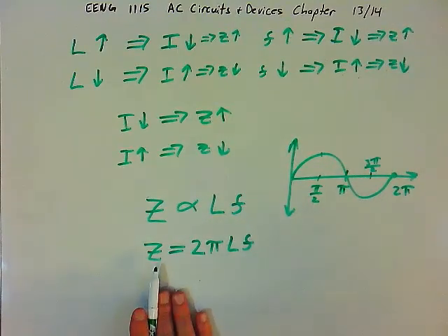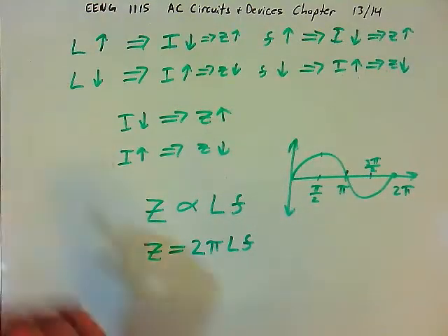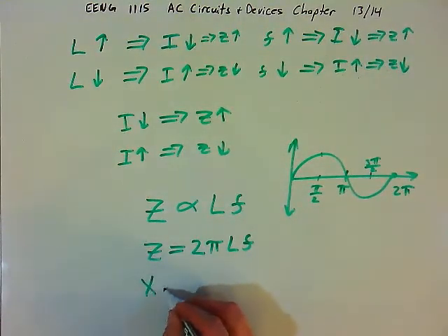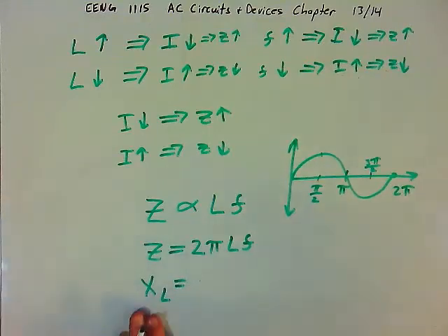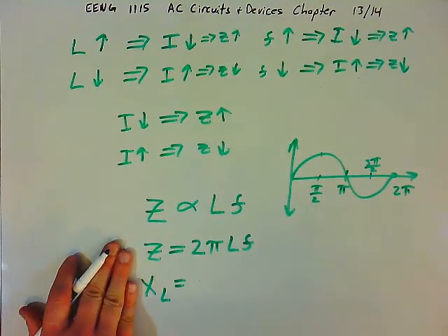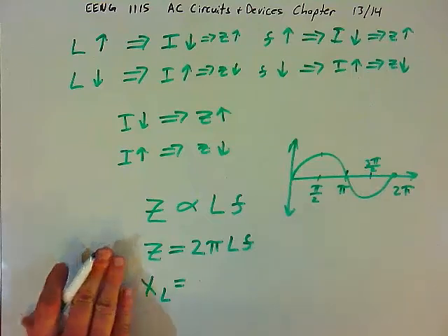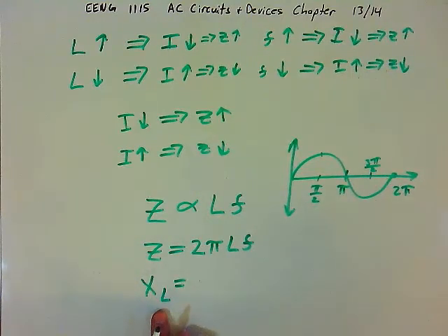And so impedance technically means the combination of resistance and what we call reactance. The inductor itself in the circuit only contributes what we call the reactance. So we've only seen circuits with inductor so far. We've not mixed an inductor and a resistor. And so I've been calling this impedance so far. Technically that's true. But when we go to look at circuits that have resistors and inductors, we want to make sure that we know that the inductor offers what we call reactance, right?